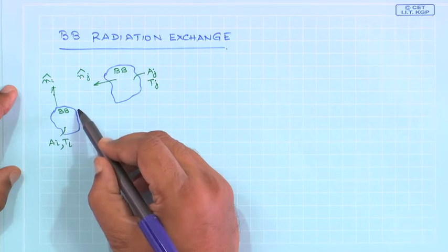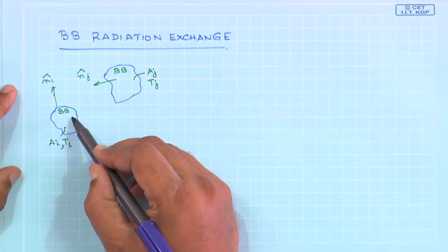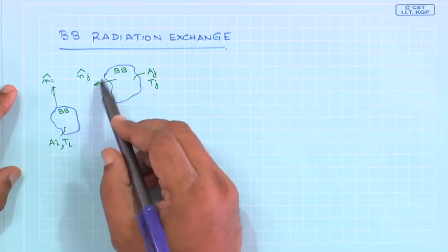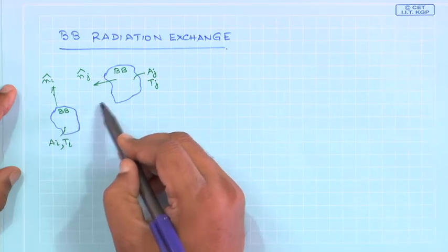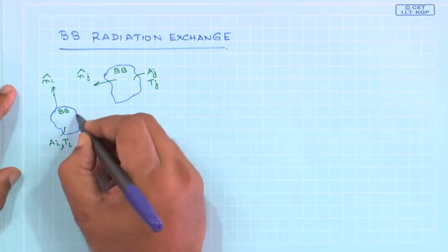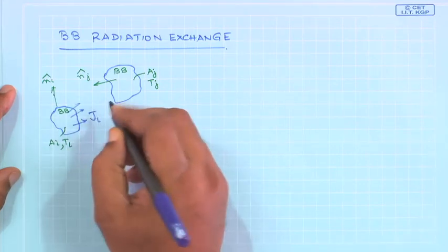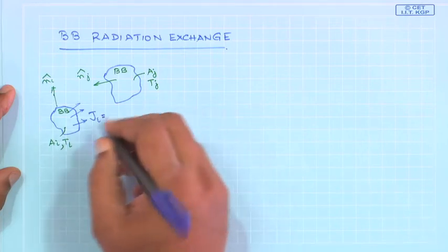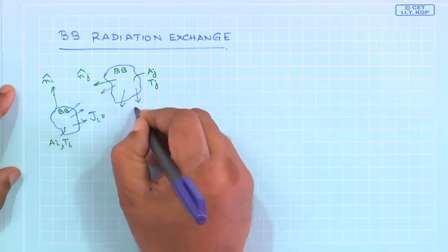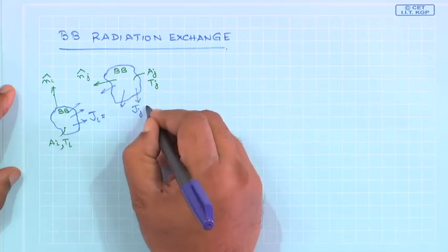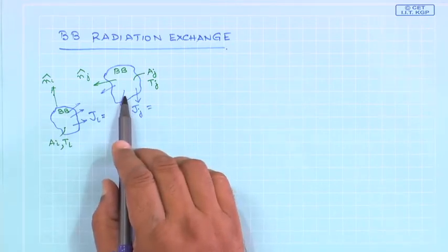When an observer sees the blackbody, it sees not only its emissive power, it also sees whatever emission coming from J getting reflected from B, and therefore what it sees coming out as emissions is Ji, which we are going to find out. Similarly, the emission coming out from over here is going to be the radiosity of the object.